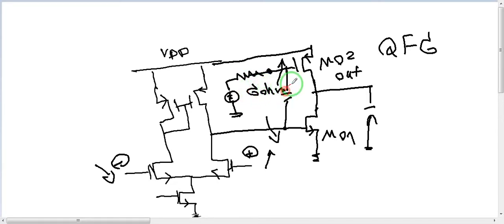So this guy cannot discharge, and here also is the gate of the transistor MO2. As you can see, the variation over here will be, sorry, this node goes up, the variation over here will be over here, and we have a significant effect on the slew rate.